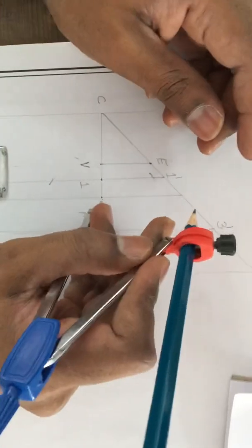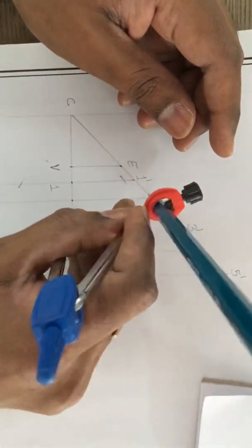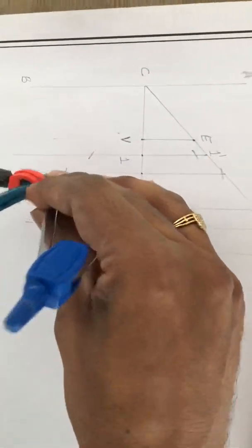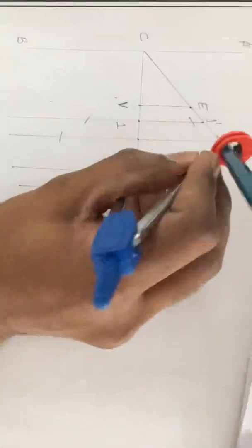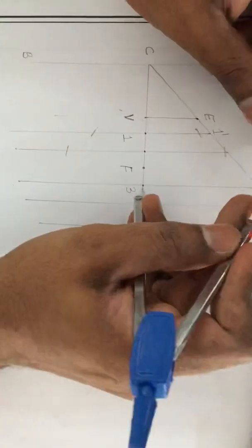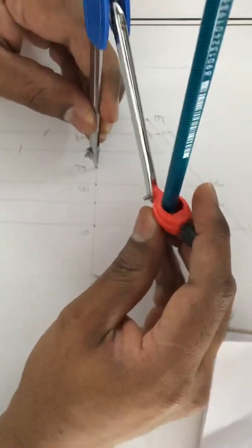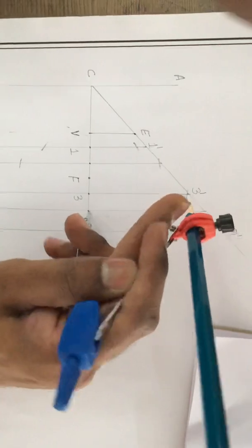below. Let next 2 2 dash be the radius and F the focus, cutting the line, whichever line you have taken the radius for. So 1 1 dash cuts the 1 1 line; 2 2 dash is the radius, go to the focus as the center and cut the 2 2 dash line. Later, for the number of lines you have located, that many radii you are supposed to take. Now I am working with 3 3 dash as the radius, F as the center, so cut above and below that line. Later, 4 4 dash is the radius.